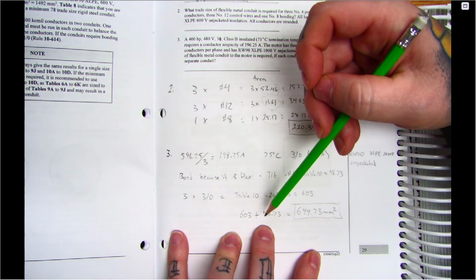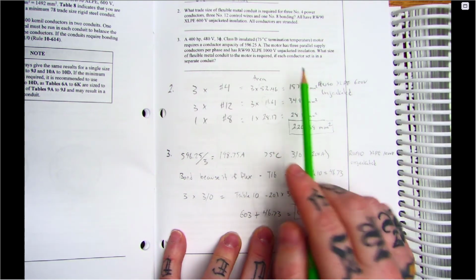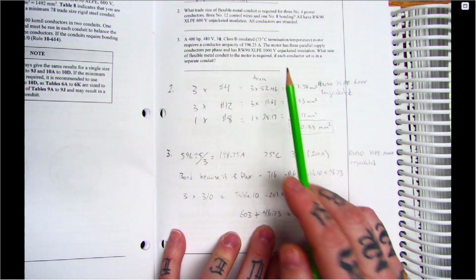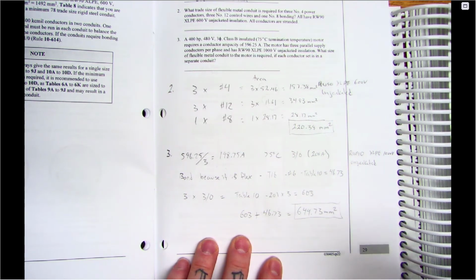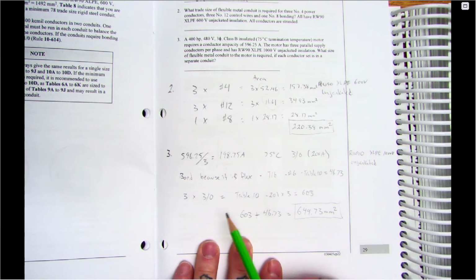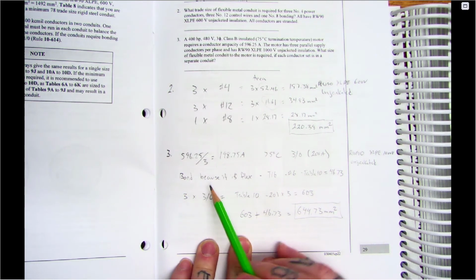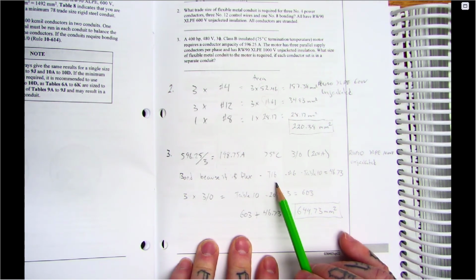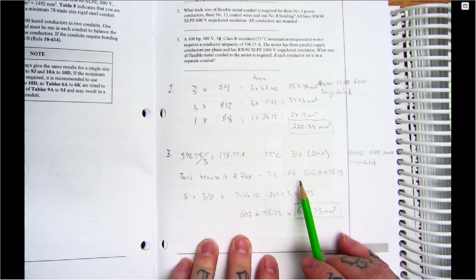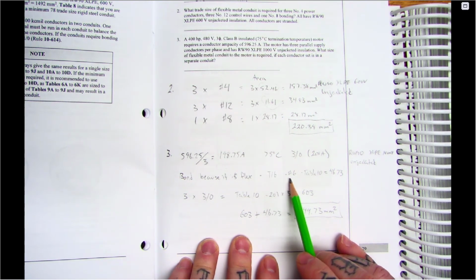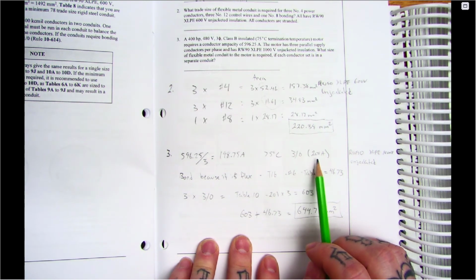Now the last thing we've got to do is not forget that these are run in flexible metal conduit to the motor. And we often do have a run of flex to a motor or a piece of machinery that potentially vibrates or moves, because we don't want a rigid connection there. So if we do have flex, then we need to have a bond. They didn't tell us there was a bond again, but we need to know that. So for the bond, because it's flex, I go to Table 16. Off of that table, I find I need a number 6 going off of the 200 amp. I think I went off the wire, the conductor size there.